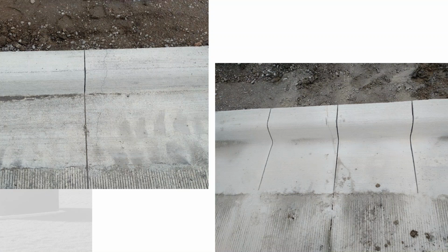Saw cutting was typically done within the first 2 hours of curing. As soon as they could get on with the early entry saws, then they were on their saw cutting. This is a photo of a curb that was maybe saw cut a bit late. So you can see on the left there's a crack that has formed next to the saw cut. So we had them actually cut that out. You can see on the right, they had a saw cut on each side of that and poured a new piece of curb. That was the only saw cutting issue we had on the whole project. There was no cracking where there shouldn't be outside of this.